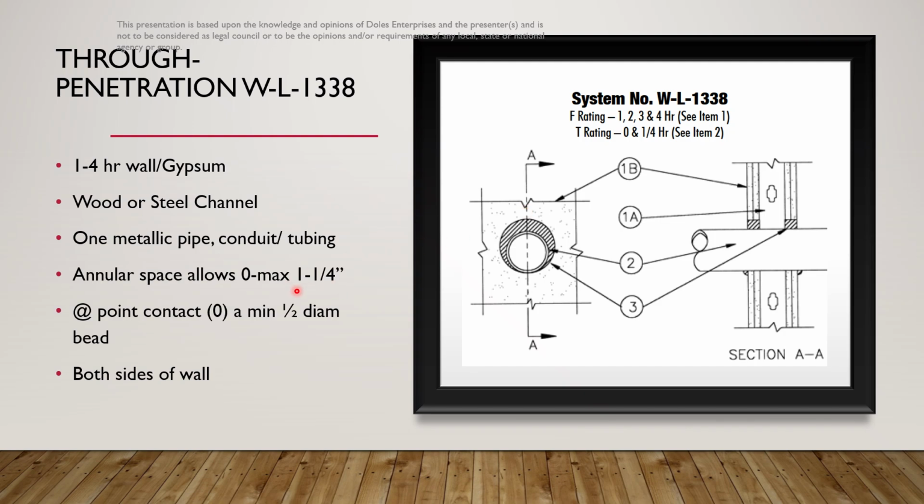In this case, we would go back to the firestop manufacturer and installer and ask them to provide another UL system sheet that shows compliance with the installed system, or to alter, change, amend the actual installation to comply with the UL system provided. These are the kind of examples you're going to run into in the field quite often, where either the opening is too large, the annular space cannot be correctly filled, the annular space is not protected.